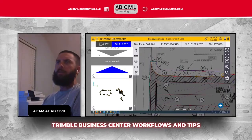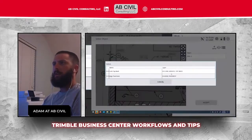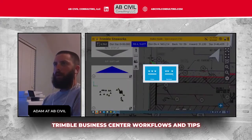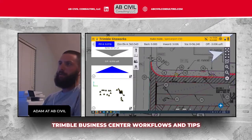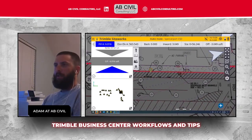So in these emulators, you can even stake an object. I name every line. Always name lines. Stake edge of pavement. Stake a line. Put it on random. It's showing me I have these configured offset 3 feet, and it even cycles through a horizontal tolerance. They make it pretty realistic.